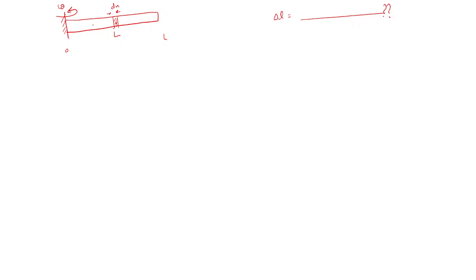Now let me know which part will put the centrifugal force here. Area is A and its length I already told, X, L. Let's suppose from here we are measuring it is X, not till here, till here. It is X and its length is dx and total length is L, so this would be L minus X, right?